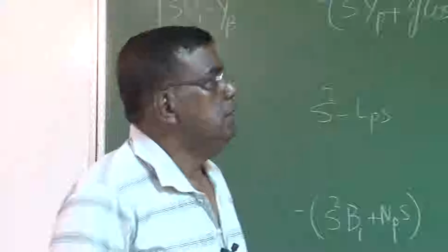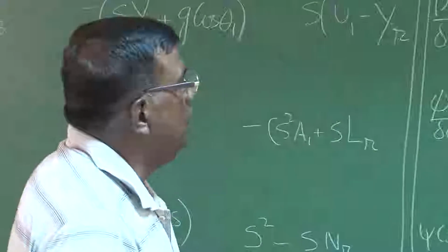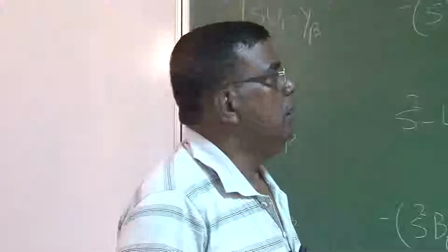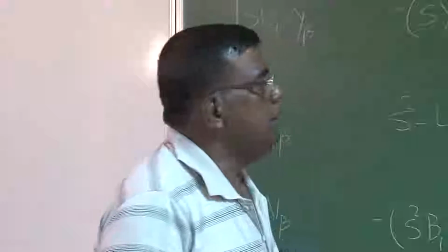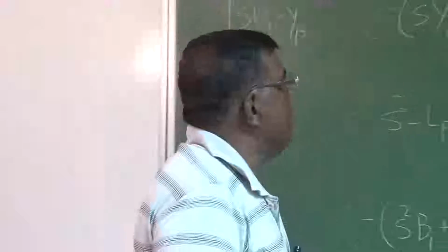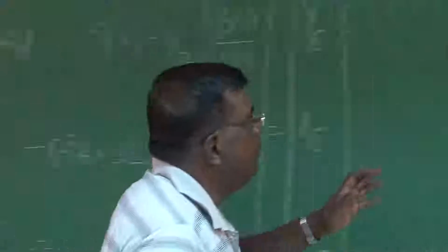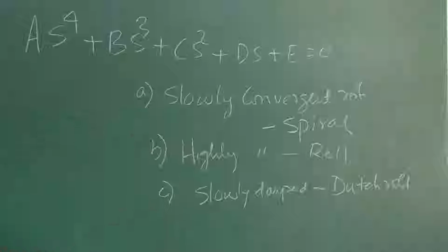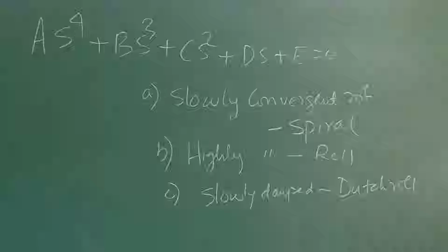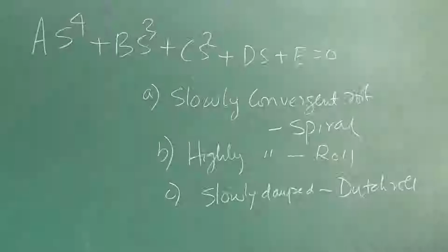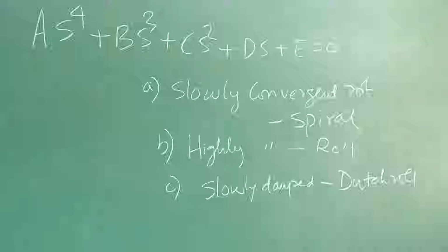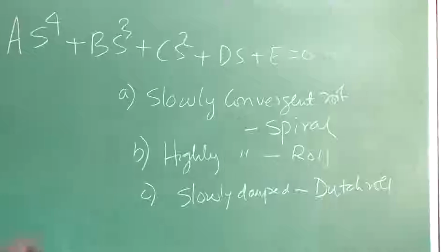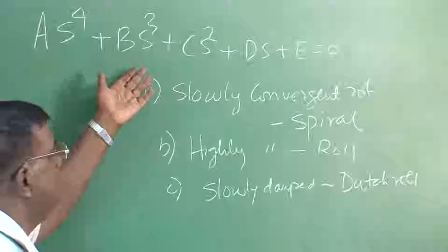Good morning, friends. We will be continuing the lateral directional case. We are trying to get interpretation via the roots of this characteristic equation. And you know all this A, B, C, D, E, they can be easily computed once I know the lateral directional dimensional derivatives. And we have seen generally for most of the aircraft, you get roots like this.